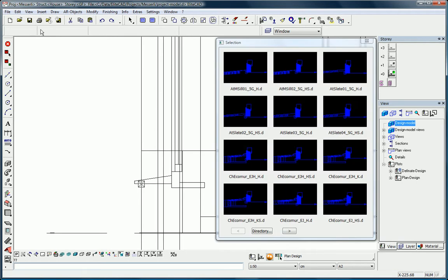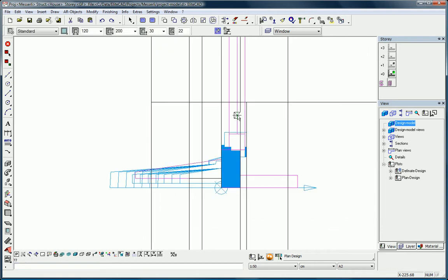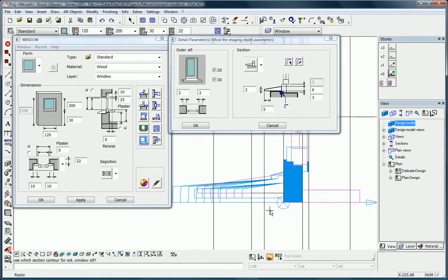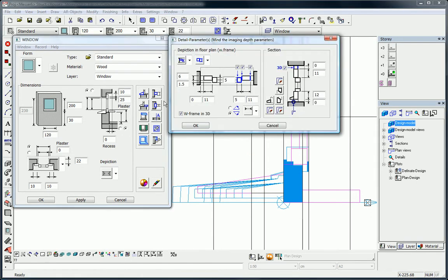Here, for example, when specialized windowsill, frame and wing profile components are required, we can use details from the extensive library, set them into the section drawing, and then apply the information to the whole component. Such information is not just available within this sectional view, but all the windows that possess these properties also display this information. Here we select the windowsill, window frames and wing profiles, define exactly where they should lie, and also define the reference values. These can easily be achieved by simple clicking on a drawing.